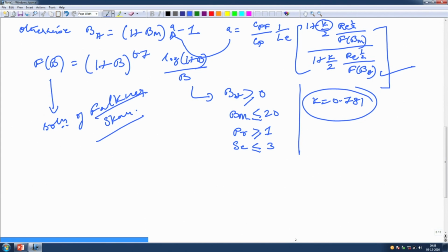So, this is a really ingenious way that Sirignano and Abramzon used to solve it. They took the droplet piecewise, locally, to behave like a Faulkner-Skan type of solution. Locally they are like wedges, right. And then they used the similarity solutions that we did in the last lecture, F''' + F F'' = 0. That similarity solution, of course in Faulkner-Skan, is a little bit different. They used that to find expressions for Nusselt number, Sherwood number and mass flux, because that is what you need for this class of solutions.